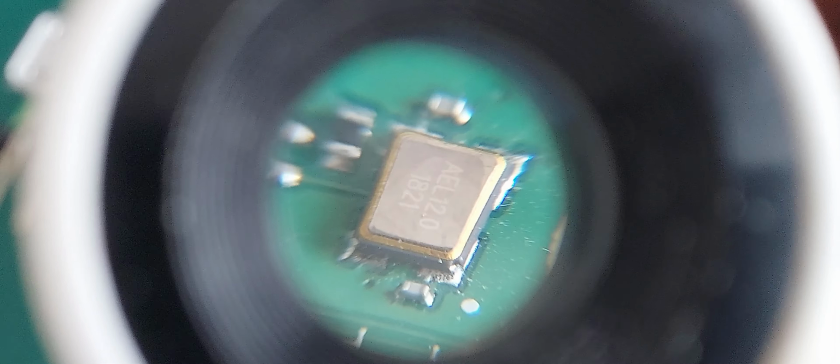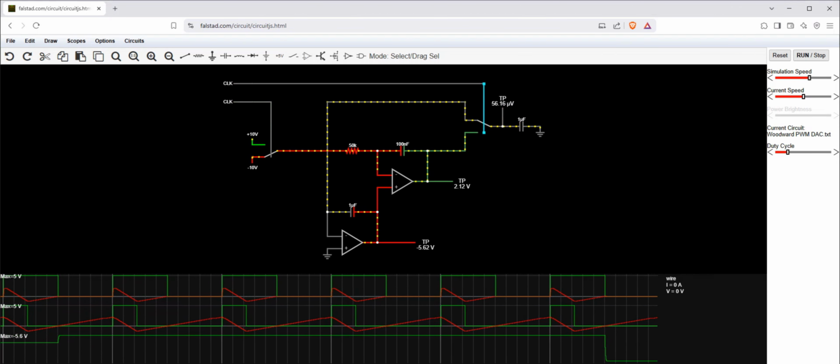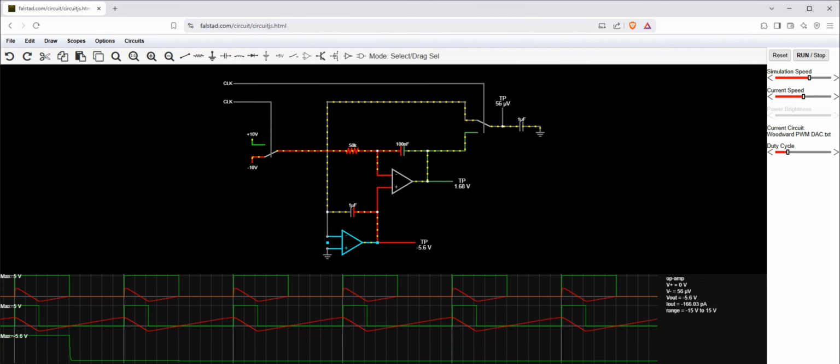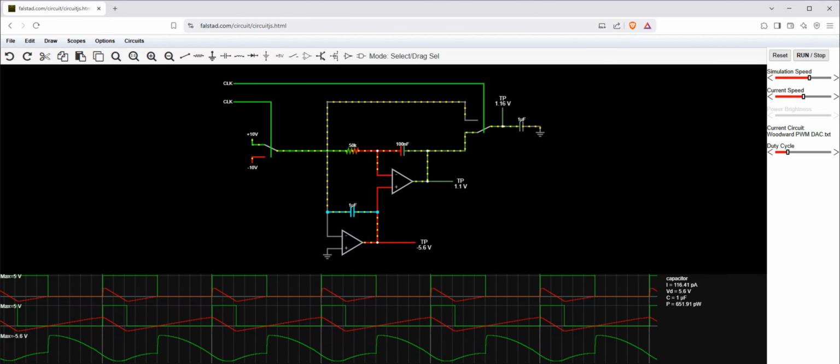If a PWM signal was fed into an ideal integrator, the output would saturate in a few cycles. What the Woodward design does is to sample the integrator waveform using a sampling capacitor driven with a 50% duty cycle and feed the sample voltage through another integrator wrapped around the hold capacitor, back to the first integrator op-amp's non-inverting input. This has the effect of skewing the current flowing into and out of the summing junction exactly such that the integrator remains balanced.